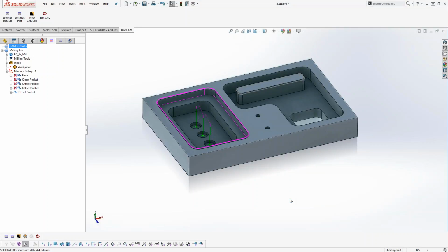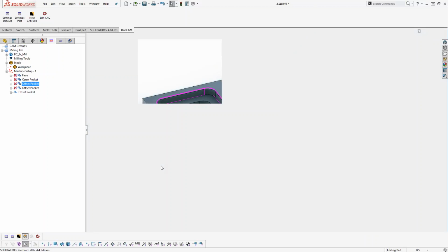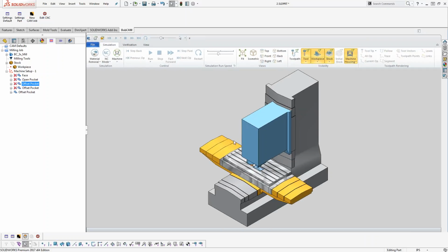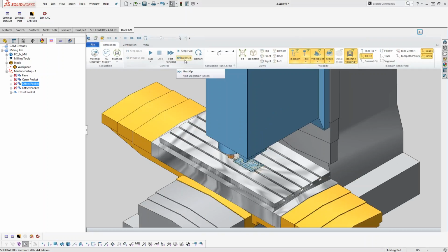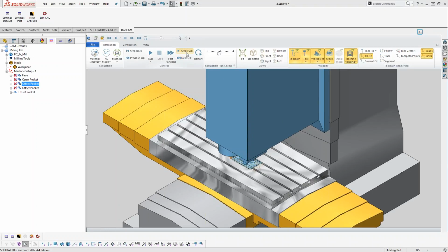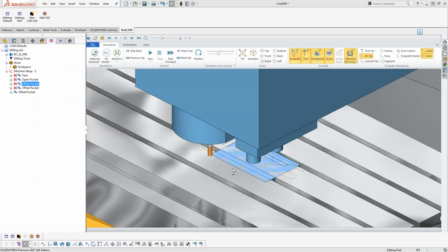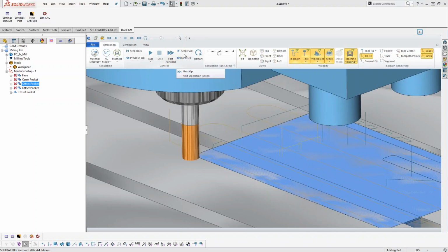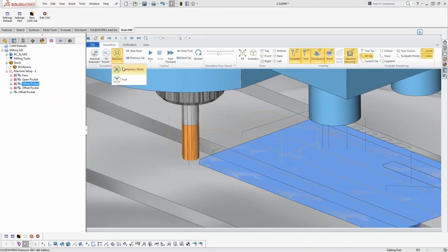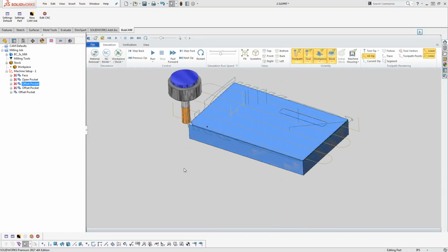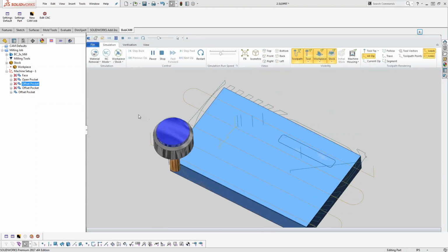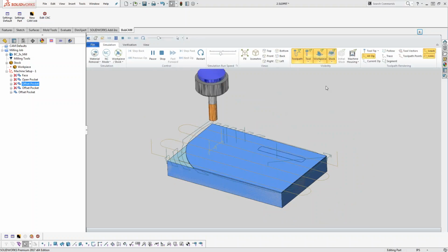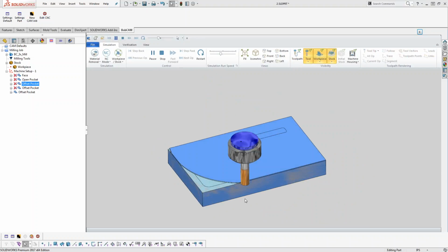All right, so by removing the table from the checking group, the tool shouldn't show a collision there because it's no longer checking for that. So we'll run that through. Let's see if it shows up now. Let me step it forward. Let's go next stop. Step, step, step. All right, so you can see I don't have this as a checking group anymore. So as the tool moves along in my simulation, it's not going to show up red anymore. Okay, so if you guys were unaware of that, that is one way in which you can handle that.